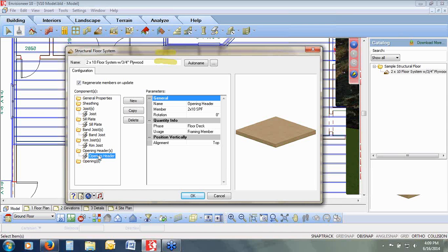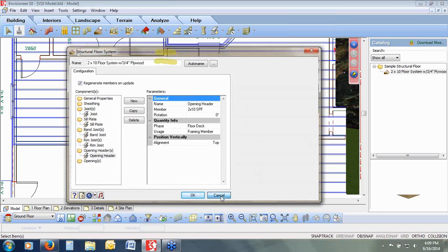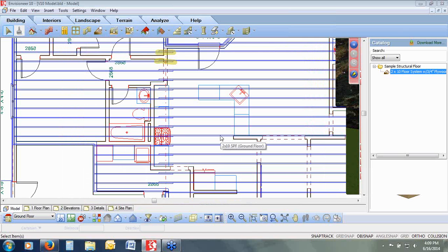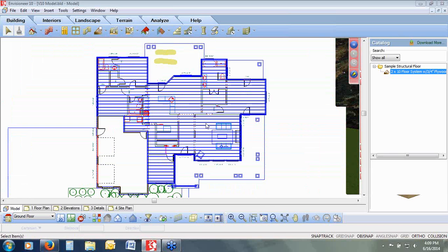then once you have them in, you can put that bearing line in like I did, automatically overlapping all of the joists. You also have the opportunity with that to break these into different sections, so I can break the floor as well and reorientate the joists so they're going in a different direction, part of that. So very easily now you can manipulate the floor, changing the shape of it, showing it bearing lines so it can automatically update that, putting in different members. When you want to cut the floor, cut the opening, you can do that as well.